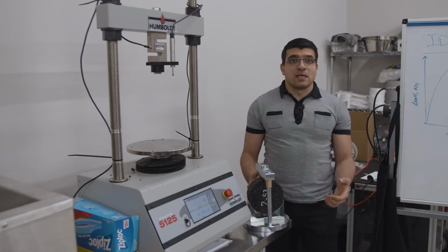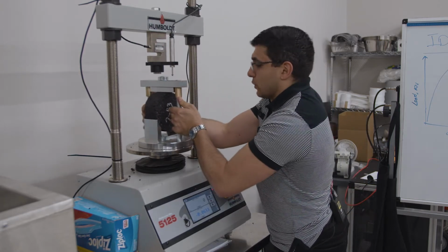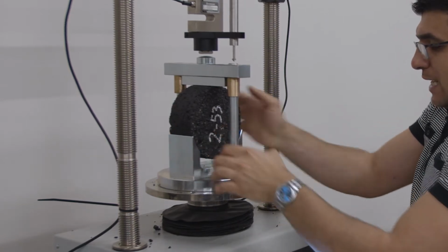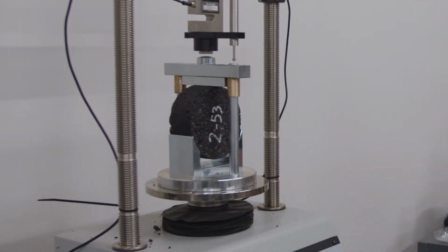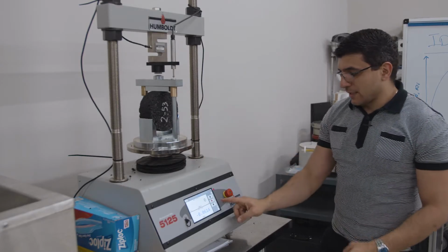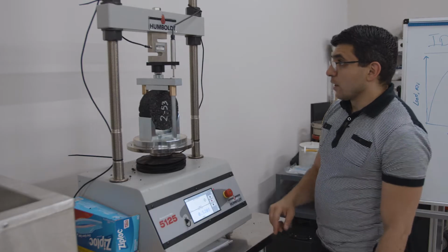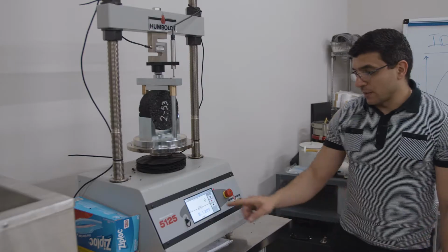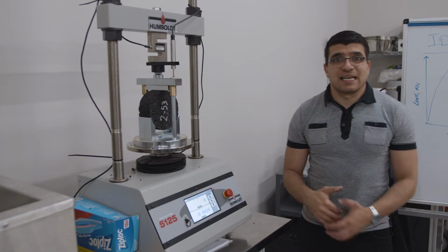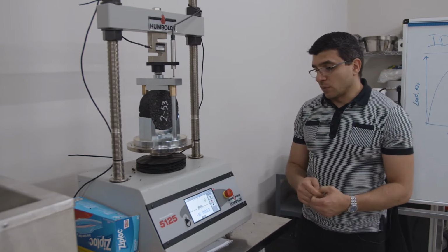Once the conditioned specimen is mounted to the jig, it is taken and mounted into the loading frame. It should be centered in the middle, and we want to make sure the LVDT from the side is properly set. From there, I'm going to bring the loading cell up. Once this happens, I want to make sure that I zero my displacement and zero my load, because my test has to start from a 0 millimeter displacement and 0 kilonewton load.